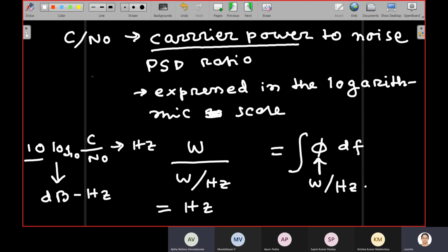Twenty represents the slope of the Bode plot. You are mixing cause and effect. So in the Bode plot, we have the amplitude of the open loop transfer function and the phase, right? And then for the amplitude, what we do, we consider 20 log 10 of G. This we plot in a semi-log graph paper, right?